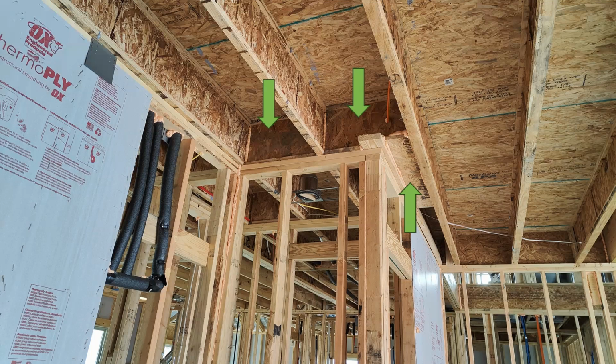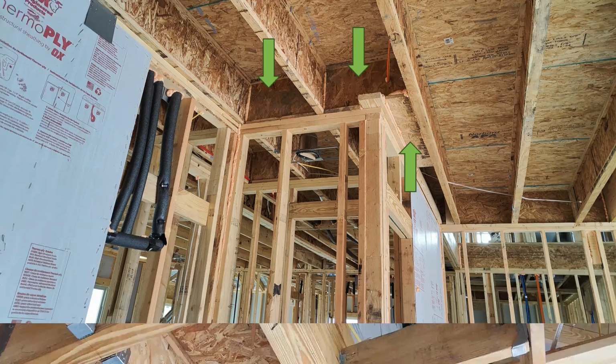All penetrations through those band joists must also be sealed. As you see, the wire penetrations are sealed, and the gaps where the TJI structures don't meet are also sealed. So you're containing the garage and the conditioned floor over the garage, self-containing it away from other conditioned subfloors. Because it's going to be insulated, it must be enclosed in an air barrier. That's why you create these band joists.